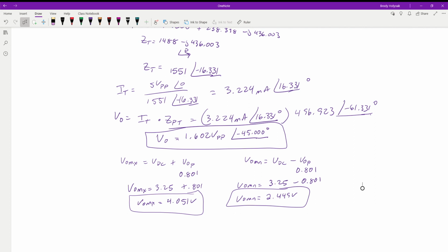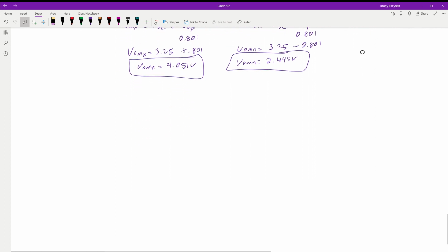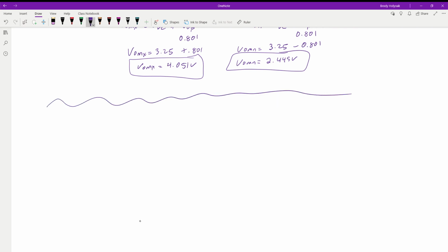Okay, so now the last step, and there's one more to do, and that will be the end of this video. We need to find our middle frequency. At what point is the voltage going to be the highest on our output? Then we can base everything in dBs off of that once we know the max output we can get. We call this our F middle. We solve that by taking our critical frequency 1, multiplying by our critical frequency 2, and taking the square root of that. So F middle is equal to